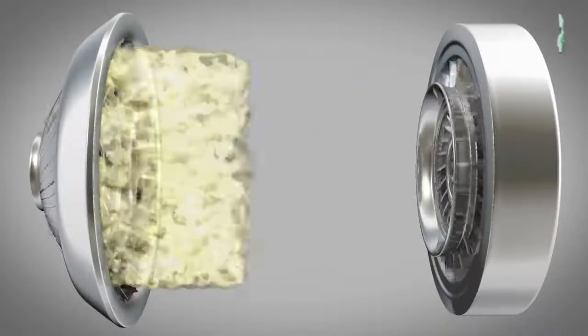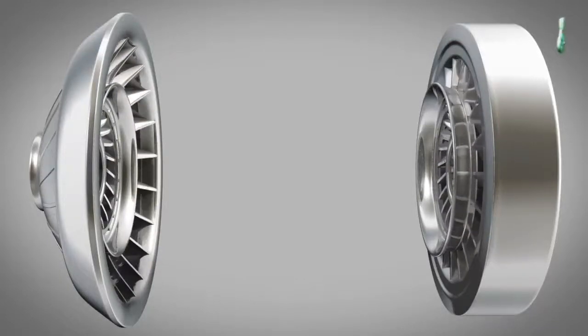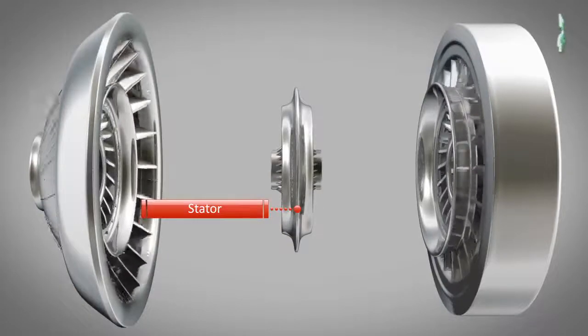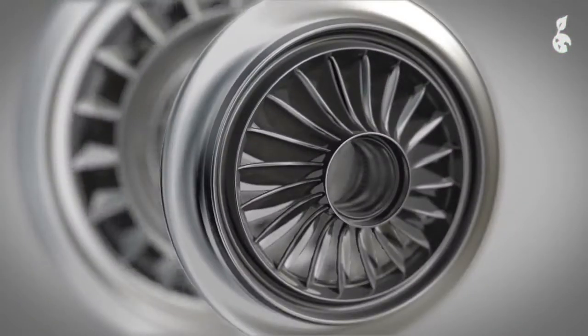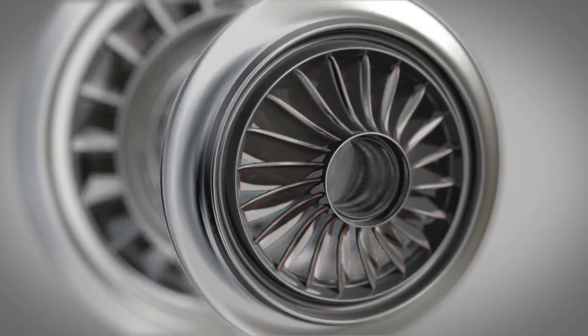Here, no torque is converted. To convert torque, another special feature is necessary: the stator, which is interposed between the impeller and the turbine. The fluid flows through the turbine to the stator. The stator's curved blades turn the fluid flow at an angle of almost 90 degrees. The result is a multiplication in torque because the fluid flows back more slowly.